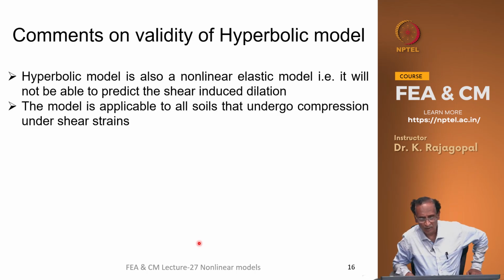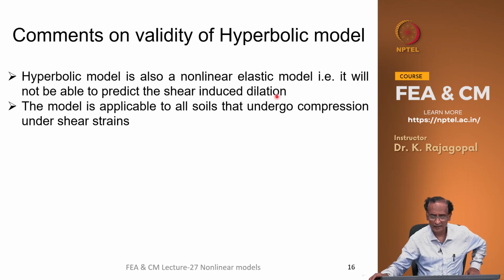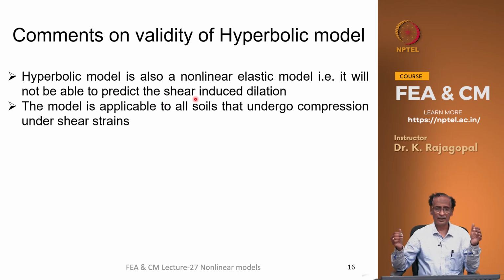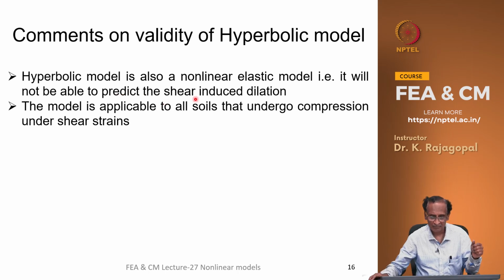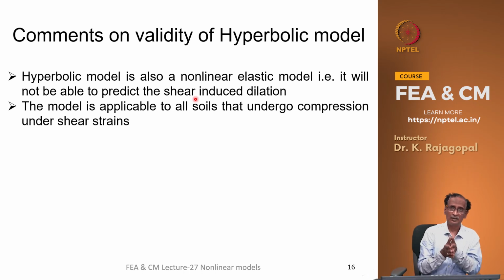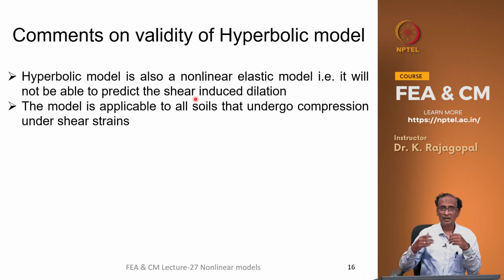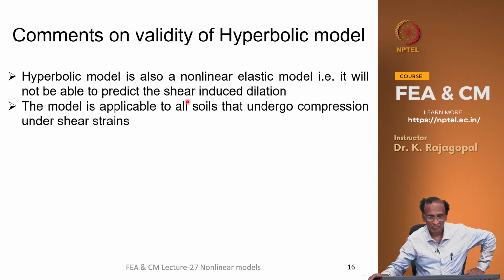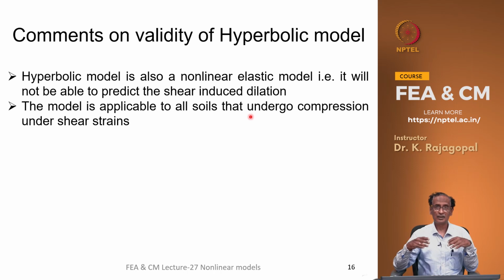And this hyperbolic model is also a nonlinear elastic model, and it will not be able to represent the shear induced dilation, but it is able to represent the effect of the confining pressure and the effect of the applied shear stresses on the modulus. And this model is applicable to all the soils that undergo volumetric compression, because basically it is an elastic model.